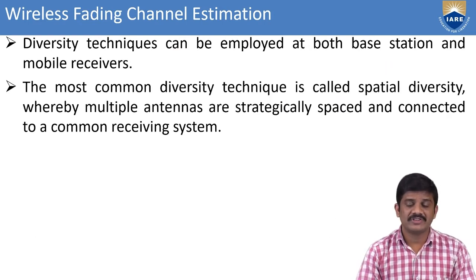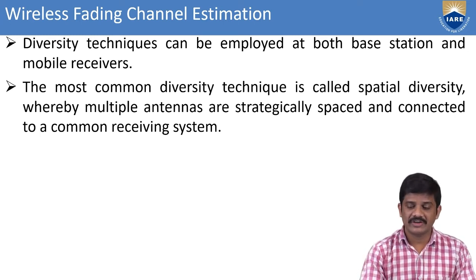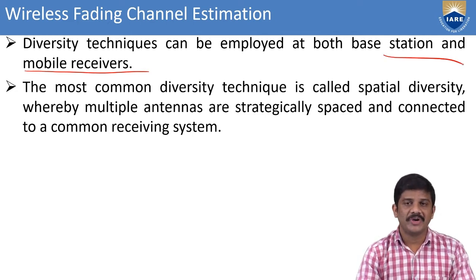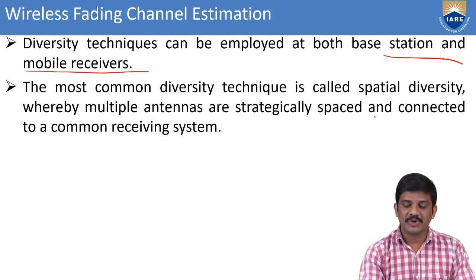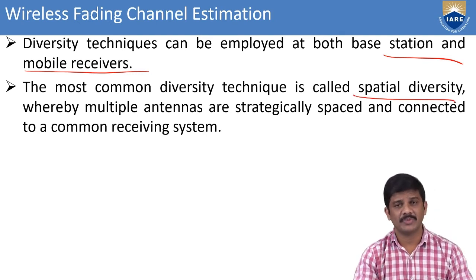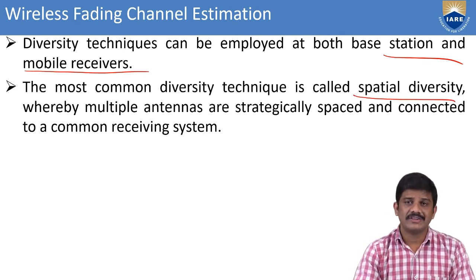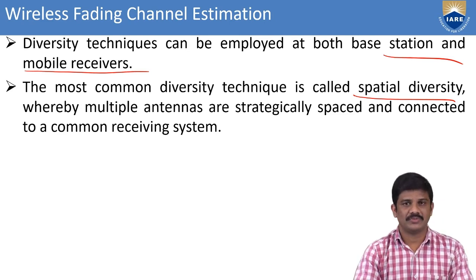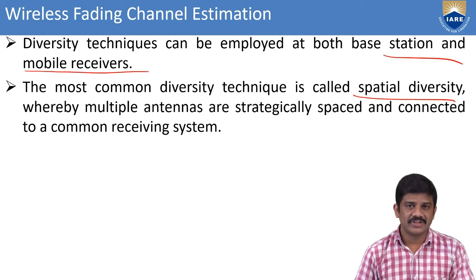Coming to diversity techniques, they can be employed at both the base station and the receiver section. The most common diversity technique is called spatial diversity. We have different types of diversity techniques, but here we consider spatial diversity, where multiple antennas are strategically spaced at one site and connected to a common receiving system. Then we can go for these diversity techniques.